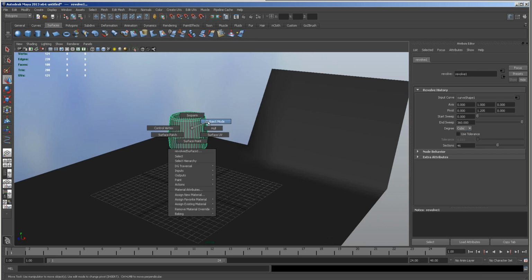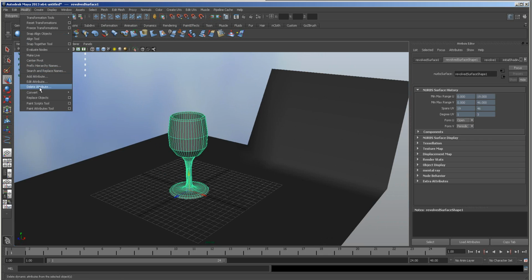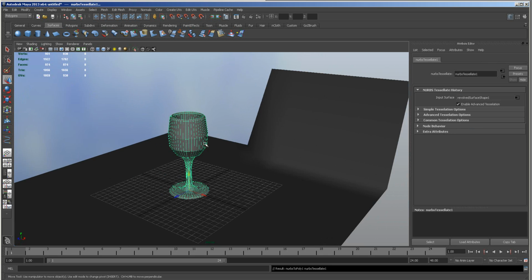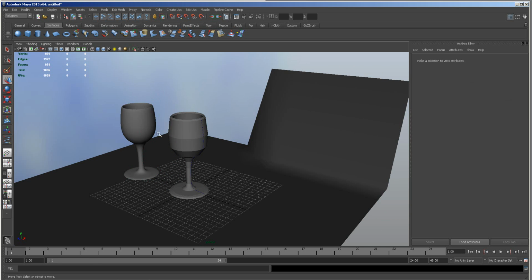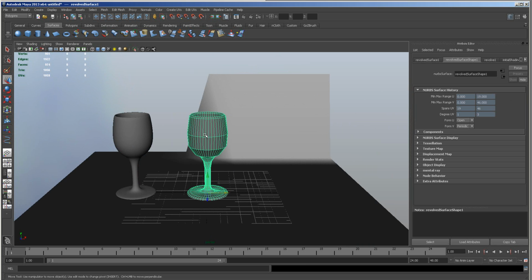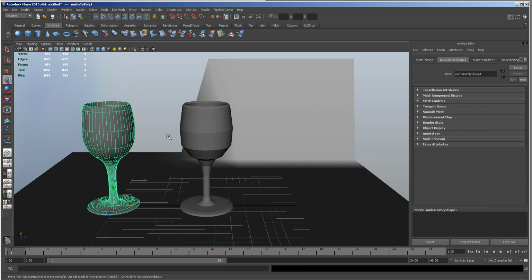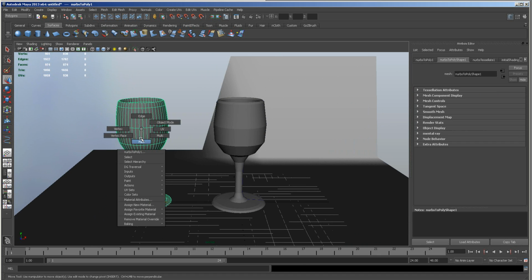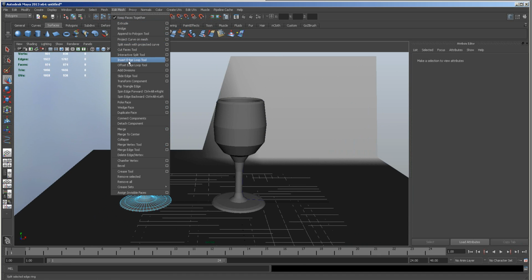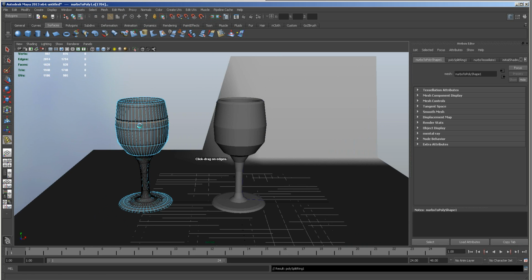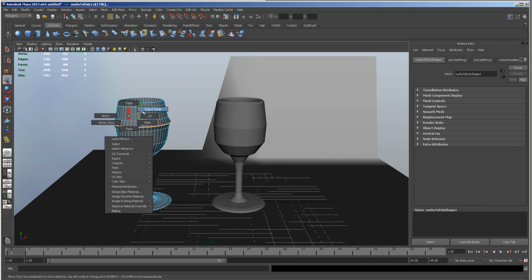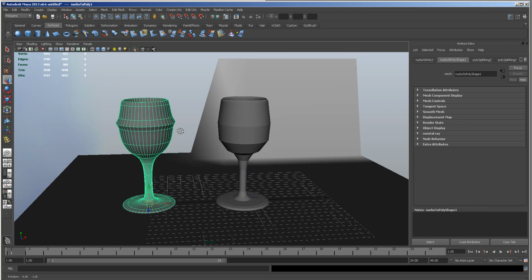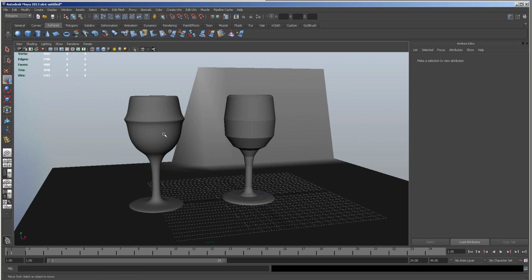and then when I'm finally happy with it as a Nurbs surface, I could then come in and convert the Nurbs to a polygon surface like that, and of course press 3 on the keyboard. So that's my Nurbs, and this is my polygon version of the Nurbs, which of course will allow you to do lots of other groovy things to it, like insert edge loops, insert one in the middle, expand it out, you know, all these kind of things. And then I could, yeah, so you got that kind of thing going on.